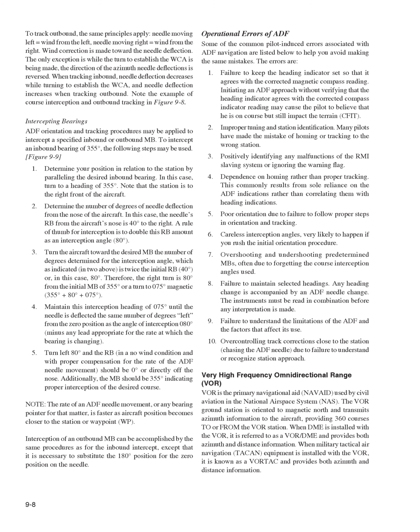9. Failure to understand the limitations of the ADF and the factors that affect its use. 10. Over-controlling track corrections close to the station, chasing the ADF needle, due to failure to understand or recognize station approach.